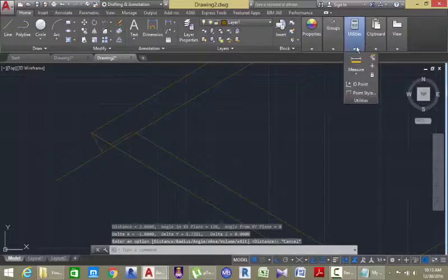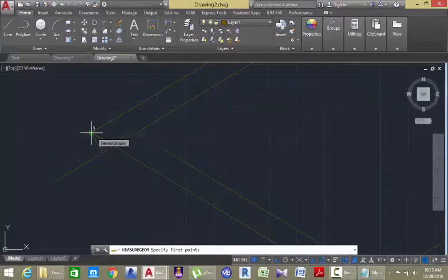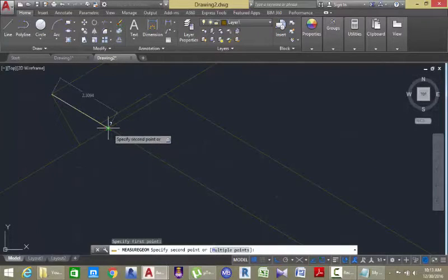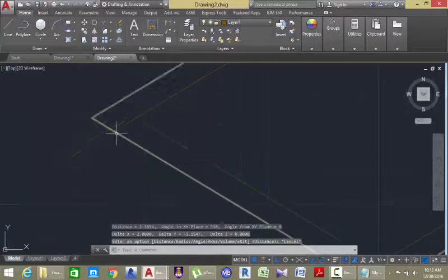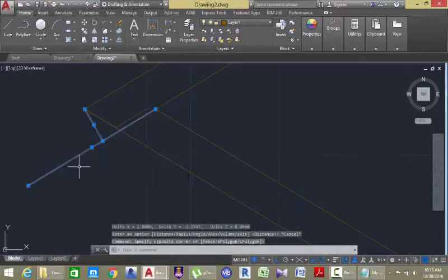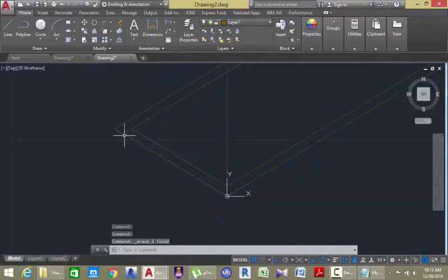But if I go to the measure command again, I try to select this endpoint, then I'm also trying to select this vertex, which is the intersection from the rectangle which I offset from the origin with the 2 unit distance. You see, I get something different. I get more than 2 units. The distance is 2.3094. So sometimes I advise you, when you are in that isometric mode, you want to take a reference from any point, use this method or use this track points method option.